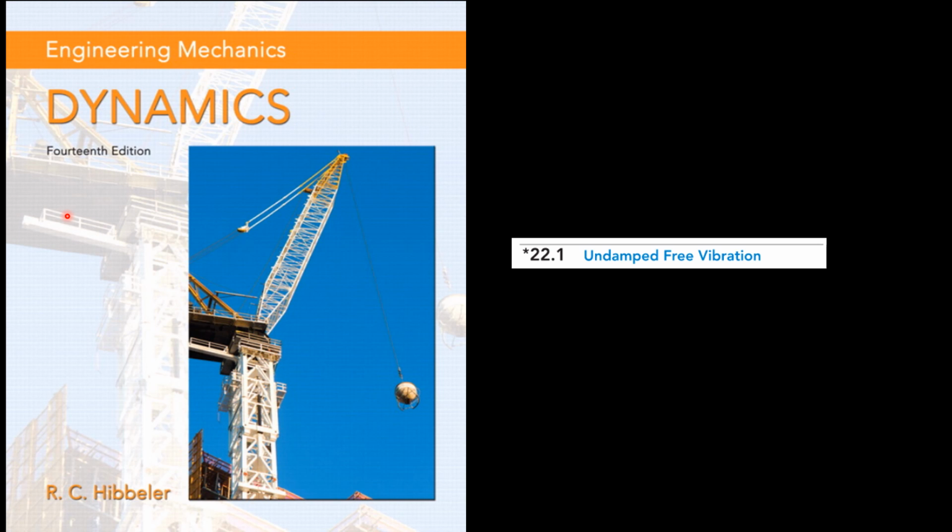But in reality, both internal and external frictional forces are present, and the motion of all vibrating bodies is actually damped. The simplest type of vibrating motion is undamped free vibration. Undamped means that we are not considering the internal and external frictional effects on a system. Free vibration happens due to gravity and or the elastic force, in this case the spring.